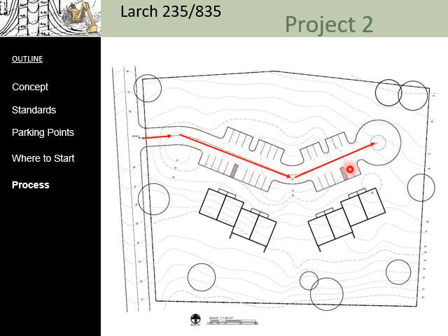So once you have some elevations figured out here, you're then simply going to go to this curb line. And you're going to say, all right, if I'm going this direction and I go 2%, I can go downhill or I can go uphill, which is preferable for you. Then I've got a curb. At that curb, you're going to go up 6 inches to get to the surface. That is the landscape area.